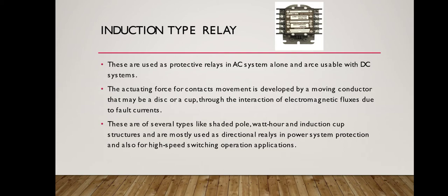There are several types, like shaded pole, watt-hour, and induction cup structures, and they are mostly used as directional relays in power system protection and also for high-speed switching applications.